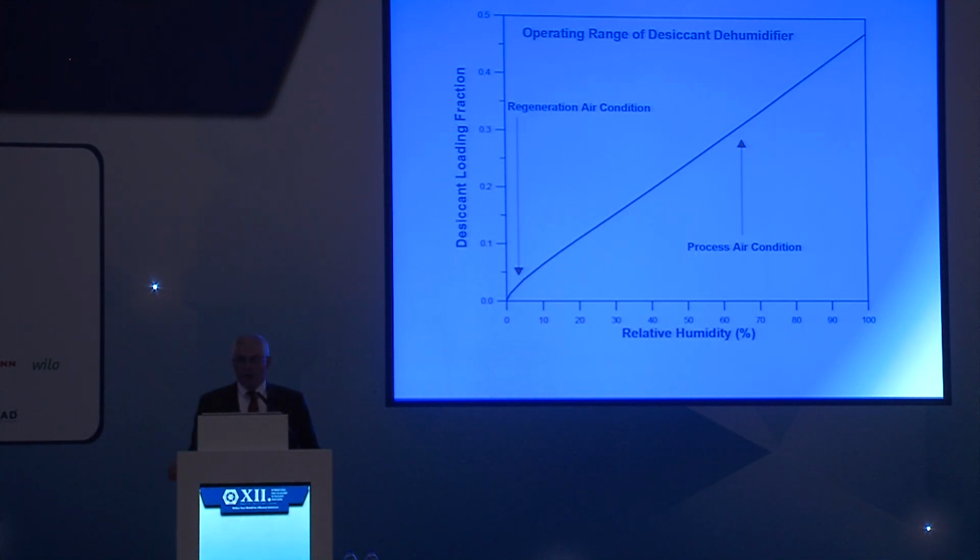So we are actually adsorbing water vapor onto the surface, and that's in the process air condition. And in the regeneration, we're actually vaporizing the water back into the airstream and getting rid of it. And that will have a performance limitation that I'll discuss in a little bit.